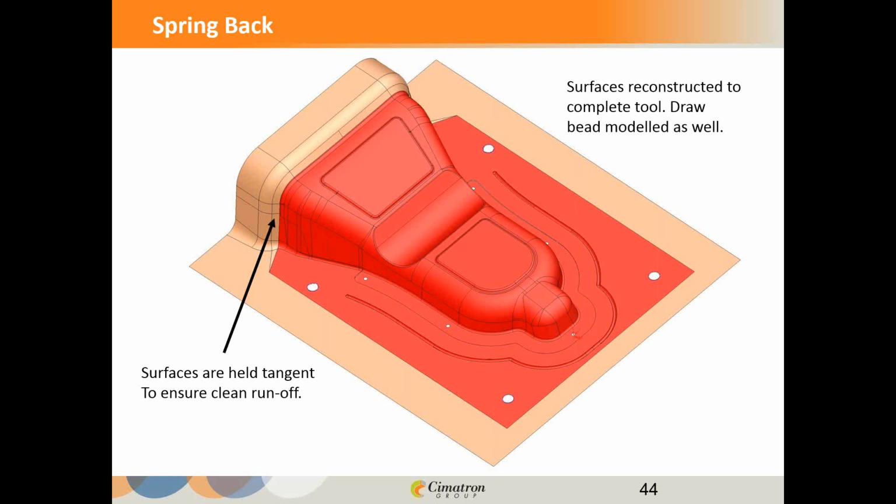With that, we'd be ready now to go back and finish up the die side by blending in the areas from the binder that we'd formed to the tool steel that was originally designed. At this time, I might go ahead and drop in the draw bead as well if I had chosen to use that. Actually model it up now as 3D.